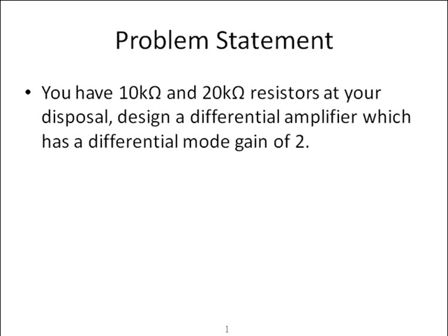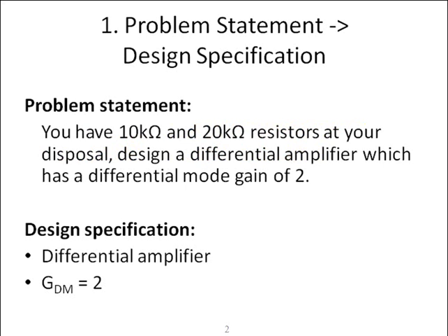This design problem is about a differential amplifier. Specifically, we'll use 10 kiloohm and 20 kiloohm resistors to design a differential amplifier. The design specifications are pretty clear from the problem statement. The desired differential mode gain is 2 for the design.